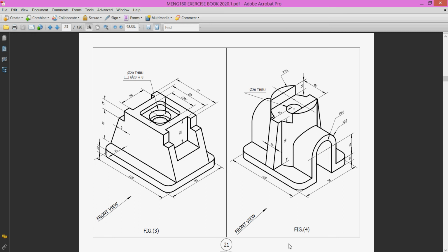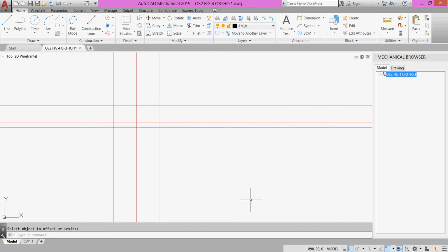In AutoCAD we have many choices. You can draw a circle here by 14 and draw lines down, and then trim. I think the best way is to offset by 14 to the right and 14 to the left, and go to our polyline, which draws lines and arcs.